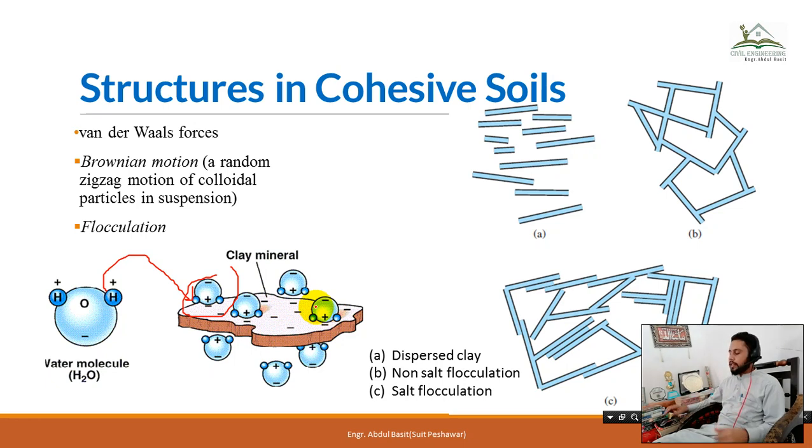Then we have another type of force that is being developed over here, that is called van der Waals forces. Okay, van der Waals forces refers to those forces which are due to the inherent property of the clay particle or the atoms of the clay particle. Okay, and all the atoms or the elements that are present in these clay particles are attracted to each other with a specific force due to the electrons and protons arrangement of the particles.